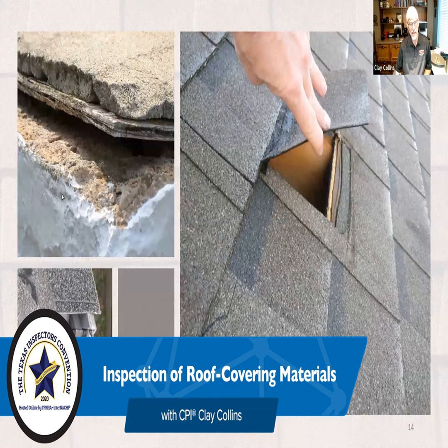And it says that asphalt shingles should be installed on roof slopes 2 in 12 or greater. 4 in 12 is the manufacturer's recommendation for the minimum slope for most asphalt shingles, unless special techniques are used for installation of the underlayment. And the underlayment would have to be installed essentially with much greater overlap.